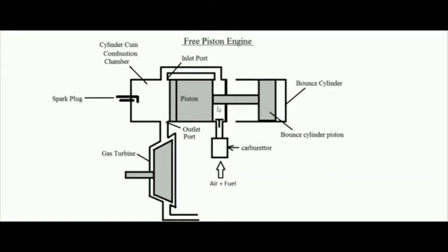Okay. Now, by the help of the arrow I am showing, this valve is a non-return valve which is ultimately connected to a duct. That duct is ultimately connected to a carburetor. So what is the job of the carburetor? The carburetor makes the mixture of air and fuel, and of course in case we are talking about a petrol engine, the fuel is petrol in that case.